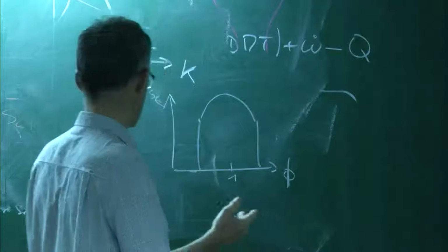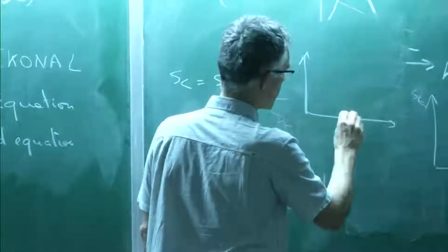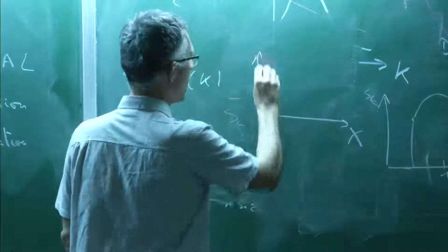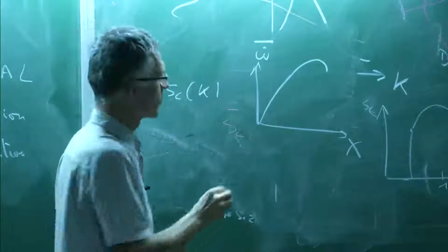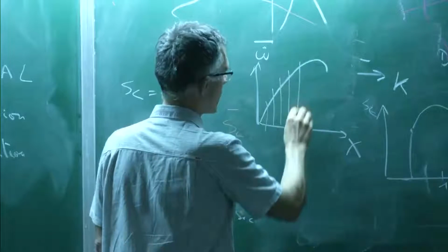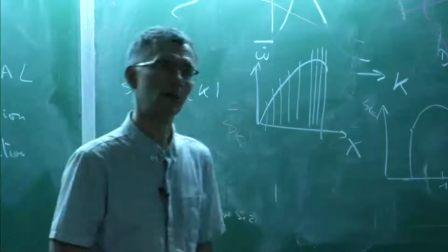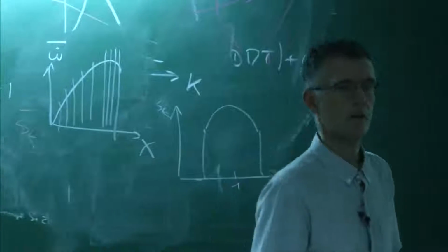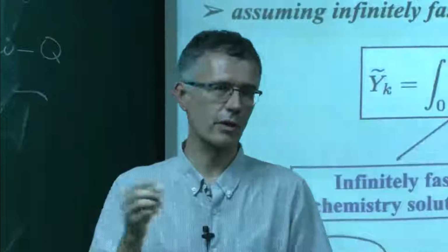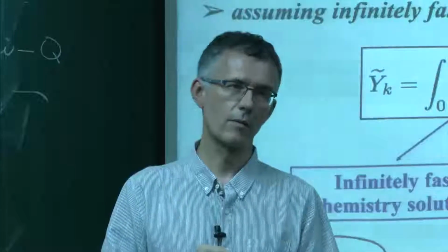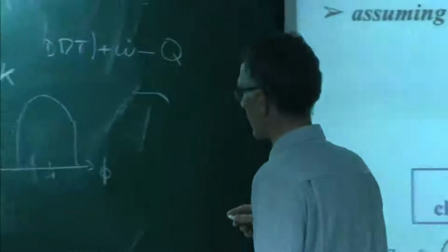If it's a diffusion flame, you have to go to this region where you have scalar dissipation and total reaction rate. It goes like this, and then it quenches here. So you might have to tabulate more flames here to be sure that you capture quenching, working up to the maximum scalar dissipation related to quenching. Those are steady flamelets, so you can run them with a 1D flame code normally. That doesn't take time, okay? It's not complicated.